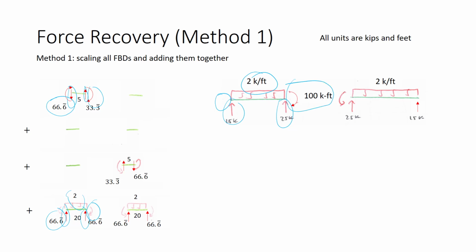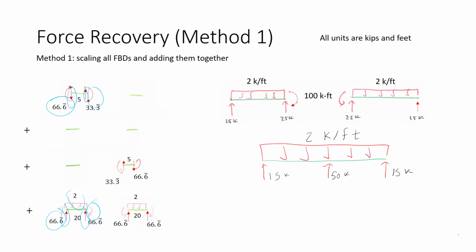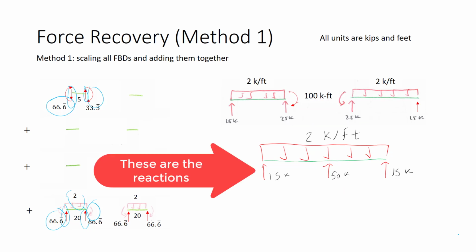The calculations on the right hand side are very similar. This problem we've seen already when we did the flexibility method, and we arrived at this very same figure. If we draw this together, we have this free body diagram. The 100 kip-foot moment is equal and opposite on both sides of the cut, so that disappears. The two 25 kip forces vertically upward become a single 50 kip force. And this is the free body diagram that we saw when we did this example in the flexibility method.